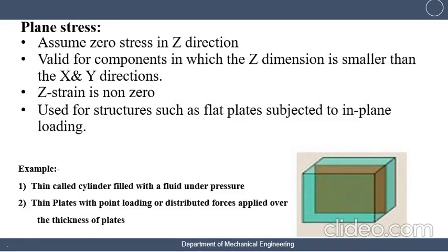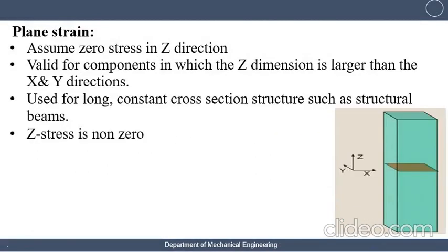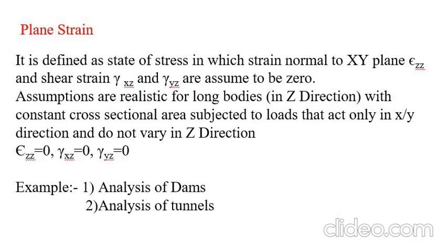The next topic is plane strain. Plane strain is defined as the state in which the strain normal to the xy plane, meaning strain zz, and shear strains xz and yz are assumed to be 0.